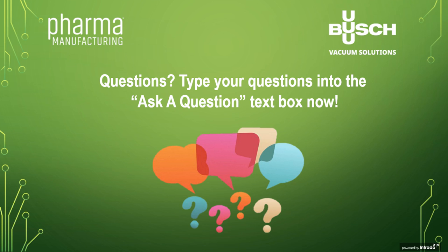I can go ahead and take that one as well. That's a good question, actually. Even though the liquid ring with the once-through system doesn't have a heat exchanger, the heat exchanger is going to have to remove essentially the same amount of BTUs that the once-through would, but it's not going to be quite as efficient. The general rule of thumb is that it's going to use about 1.5 times the water you'd have with the once-through. But the big advantage is that instead of having contaminated liquid on the discharge that you need to dispose of, it would just be going through a heating element, so you just have slightly warmed up water. But that's why it would actually require more water there.